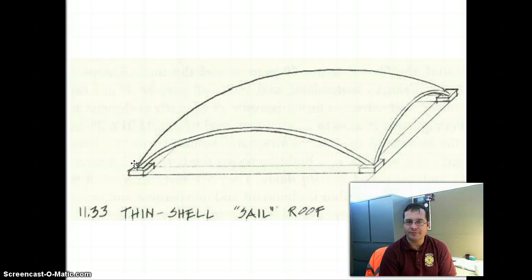The one that comes to mind for me is a tavern in Mount Vernon, Wisconsin. The Gone Fish Inn is an old masonry building, and the parapet wall on that had started to fall off. And so the repair that the property owner made there is they had shotcrete sprayed on the outside of it to kind of encase all of the bricks that were at risk of falling out on the patrons of the tavern.